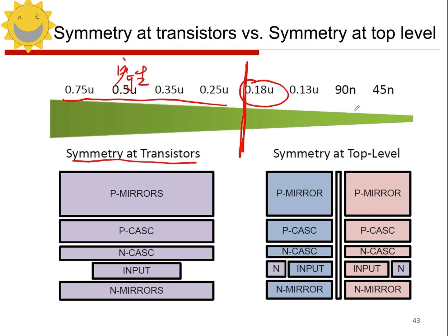So, if the parasitic problem is relatively small, I can use more complex wiring, right? More complex wiring, but as the process feature level is reduced to deep submicron or tens of nanometers, the parasitic problem is relatively large. The parasitic problem is quite serious because the distance of all metal wires will be shortened. That is, the thickness will be reduced. In this case, the parasitic problem will be aggravated. If the parasitic problem is aggravated, then if I use more complex transistor body matching, clearly this will lead to more serious parasitic issues. So, at these smaller sizes, we usually prefer to use what's called top-level matching, where I create a symmetrical structure with a central axis at the top level, and that works just fine. On the left and right, I won't do the matching for the supply core.